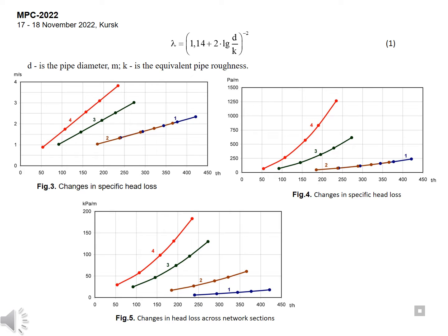Modeling of the hydraulic regime of the heating network of the first stage of construction was carried out when connecting new buildings. With an increase in flow rate and a constant diameter of the pipeline, the velocity of the liquid will increase. During the direct hydraulic calculation, the network was designed to operate in the region of a developed turbulent regime, therefore, the same regime will be maintained with an increase in flow. In this case, the Prandtl-Nikuradze formula can be used to calculate the coefficient of hydraulic friction.